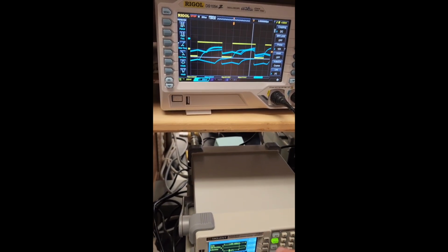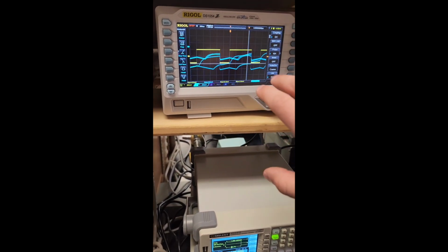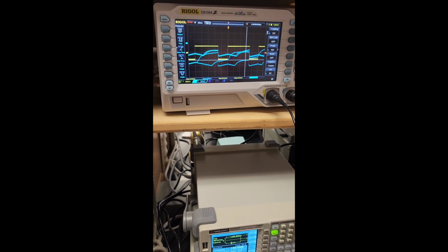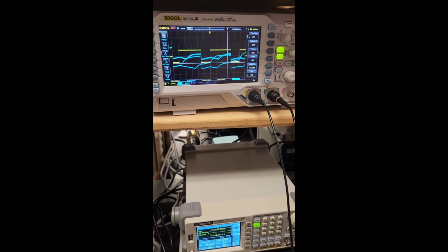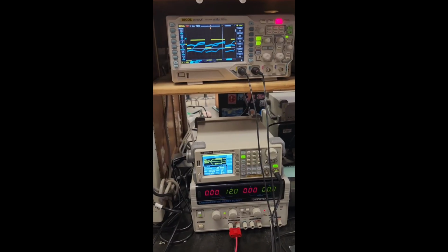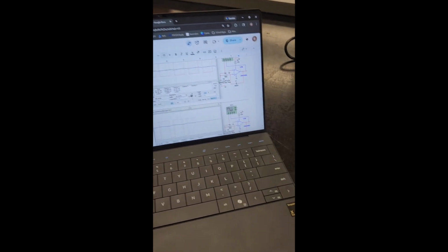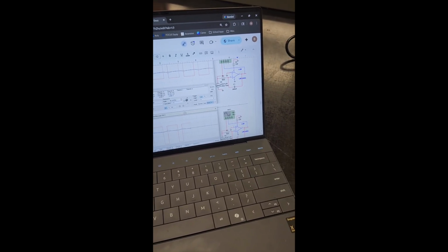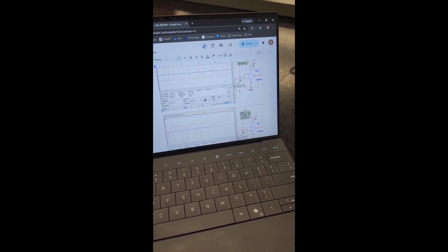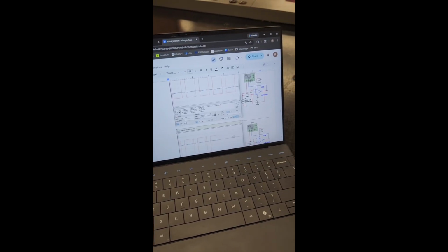we can view again this distortion and this weird sloping, as changing the duty cycle changes the period, and thus changing tau, and thus not matching our RC circuit that we designed correctly, and thus not producing the correct integrator.